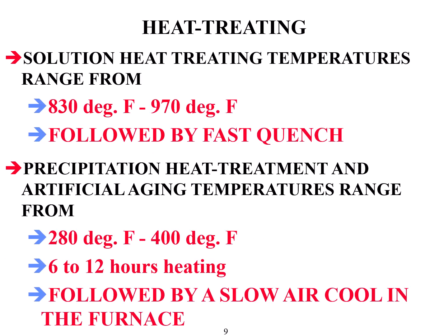The slide is kind of showing you the difference in some of these heat treating processes. Often the heat treatment varies based on the temperature that the material is brought to and how it's cooled. And different temperatures and different cooling rates produce a different hardness in the metal. This is just showing the example of why a T3 may be different than a T6, may be different than a T4. It's all about temps, times, and cooling rates.